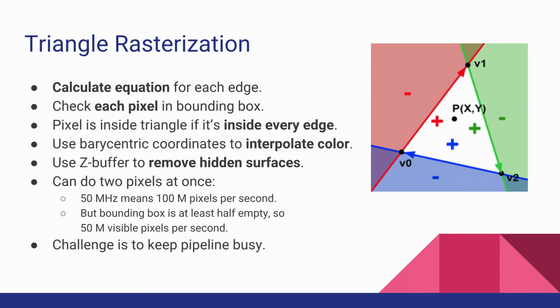The FPGA works at 50 megahertz, so I do 2 pixels per clock. So it goes like this, like that. In fact, you could have more, because it's all in FPGA. You can just instantiate more. I'll talk a bit about that later. It's kind of neat. But I do 2 pixels at a time, so I'm inspecting 100 million pixels per second.